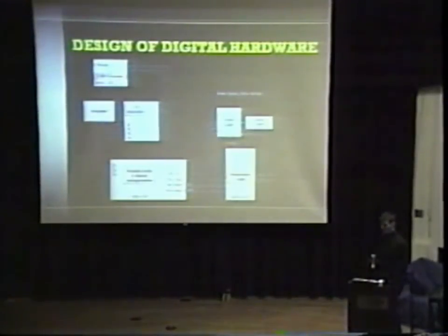Originally, the system was designed to have a faster clock operate it so that any baud rate could be produced. That also created noise in the system. As the combinational logic in this system is changing, it's complemented with D flip-flops, and those values have to reach steady state before you want to read them. If the wrong edge is caught here, the wrong value will be loaded.